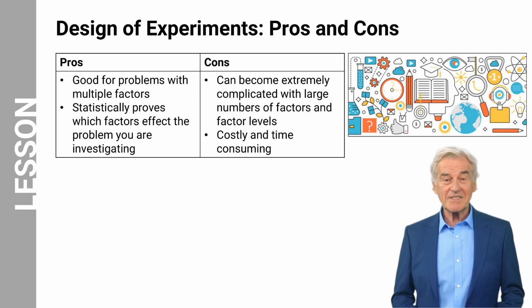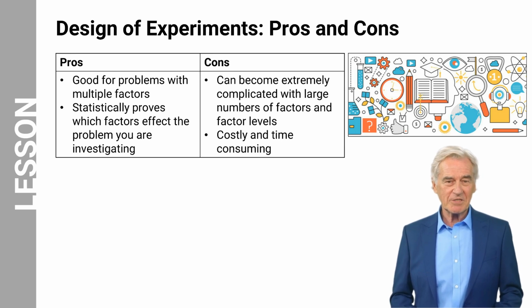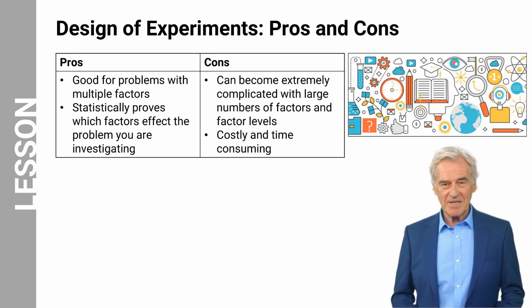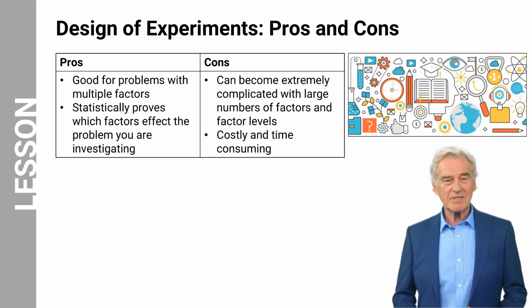Design of experiments is an effective root cause analysis tool because it statistically proves which factors are causes of the problem you're investigating. The main problem with design of experiments is that it becomes extremely complicated in situations that have large numbers of factors and factor levels. Also, it can be costly to run enough experiments to get the statistical data required for the analysis.